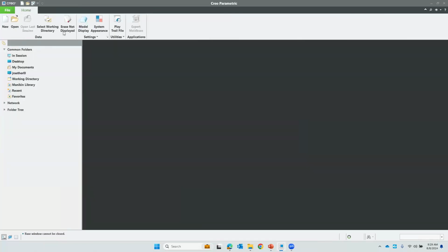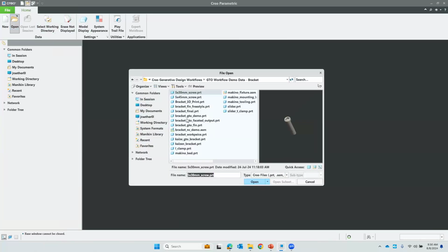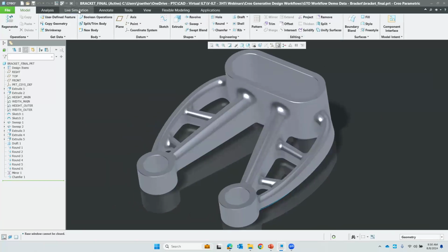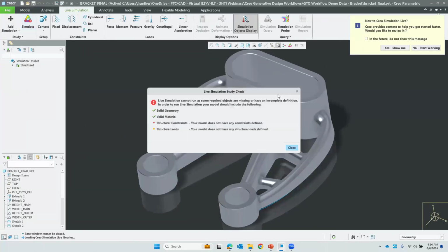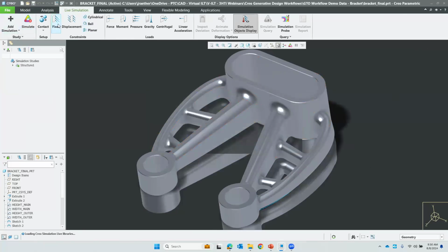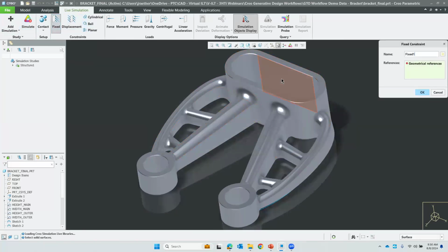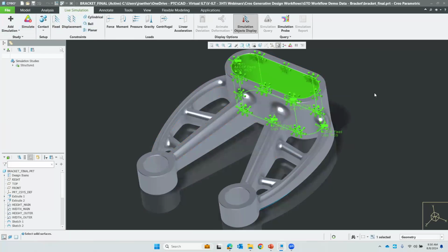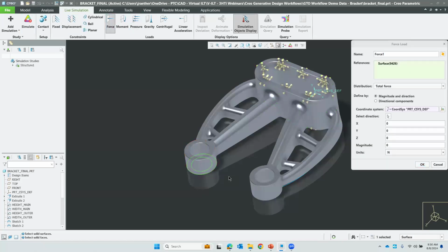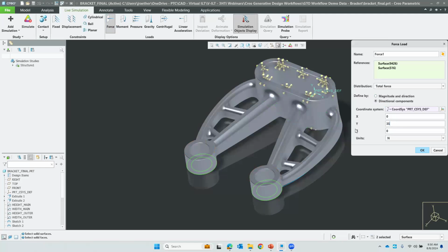Another option, again, here's where I might go into using Creo. Here's where I'm going to recreate it. But because I recreated it, I probably want to do some analysis. So with this, really quickly, and notice when I do the analysis, the way I define the analysis is the same way I created the loads in generative, in live simulation, everything. And then we have some forces down here, right, on there, and this one here. That's going to be in the Y, 3,500.